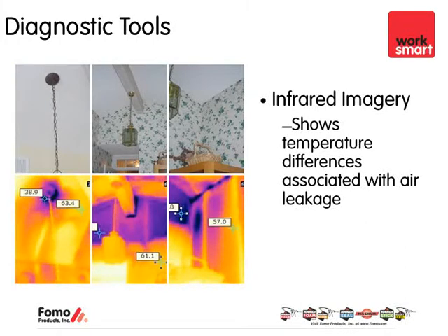And if you look below where it shows the infrared imagery, in this case, the electrical work and everything for that hanging light fixture is actually going right up into the attic. It has not been properly sealed, and where you can see the bright blue and bright purple, that means you've got a much colder temperature near that penetration going up into the attic, meaning that you're actually getting cold attic air while this house is being depressurized. It's pulling that cold attic air into the conditioned space. That's one of the prime areas that you'd want to air seal.